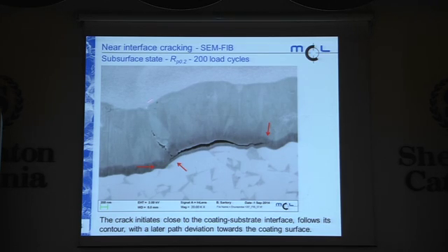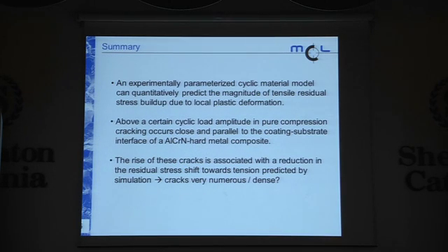So, colleagues from Leoben showed that if there's a droplet, cracks close to droplets may occur. We now show you that this is a possibility also in hard-coated tools. This may be the early stage of failure, and we also demonstrated that below the surface there can be an origin for failure. So failure in hard-coated tools is situation dependent, temperature dependent. We don't know yet, but this is an interesting story to fill the researchers' lives to clarify.